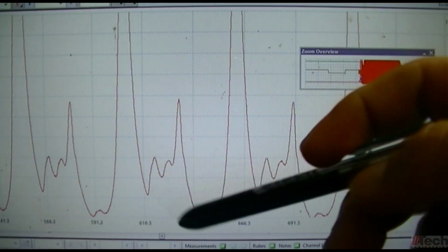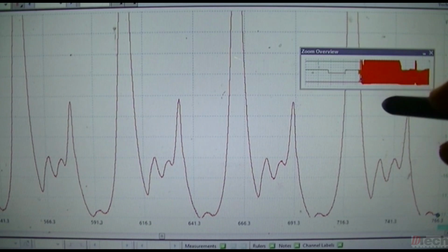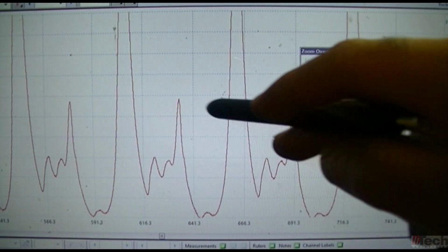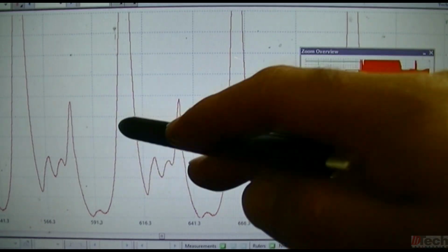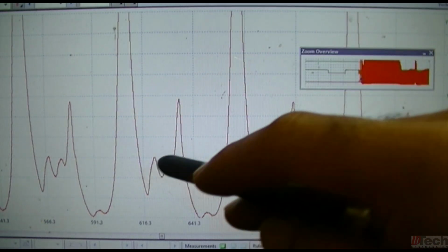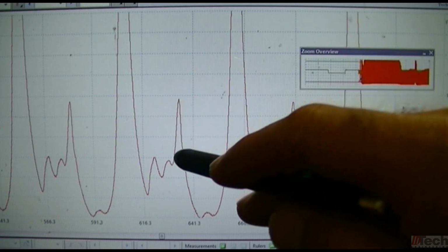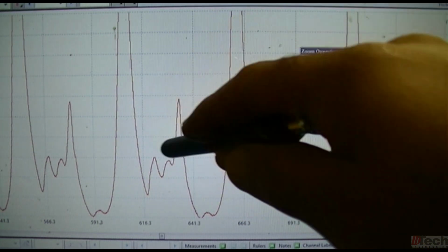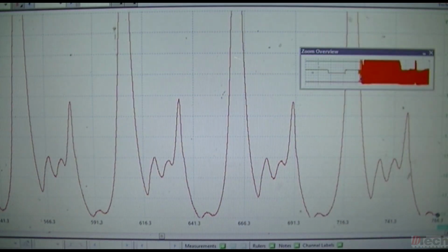Okay, so I am zoomed in towards the beginning portion of the capture, in the lower portion between the TDC points in the exhaust area, and there is that rise in pressure. I want you to pay attention as I scroll through the idle portion.